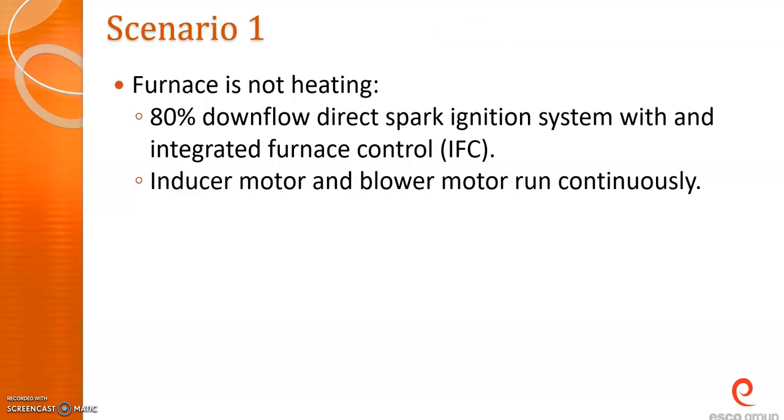So scenario number one, furnace is not heating. You're working with a direct spark ignition system and a furnace control board. You've got an inducer motor and blower motor that run continuously.